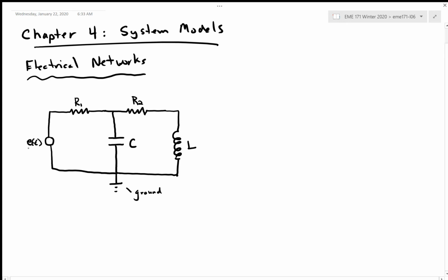You can imagine that the circle E could be supplied by a battery, or maybe you plug into the wall, whatever we got here, but 2 resistors, a capacitor, and an inductor. So we've got some basic circuit that has an R, a C, and an L, right? Those are 3 primary components that we find in electrical circuits. And we have talked about these too. These are going to be associated with inertia, resistance, and capacitance ports. Okay, and the E, the applied voltage, will be associated with an effort source, right?